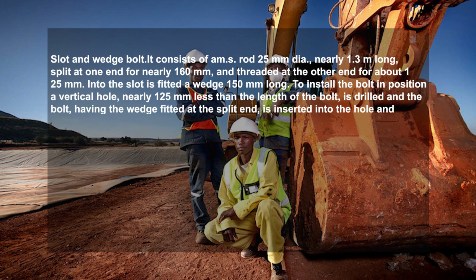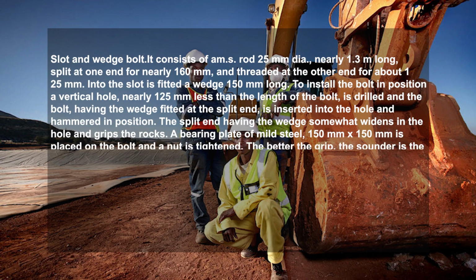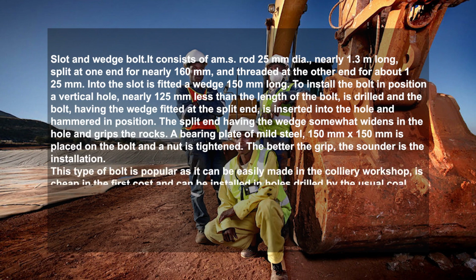It consists of an MS rod 25 mm diameter, nearly 1.3 meter long, split at one end for nearly 160 mm, and threaded at the other end for about 125 mm. Into the slot is fitted a wedge 150 mm long.